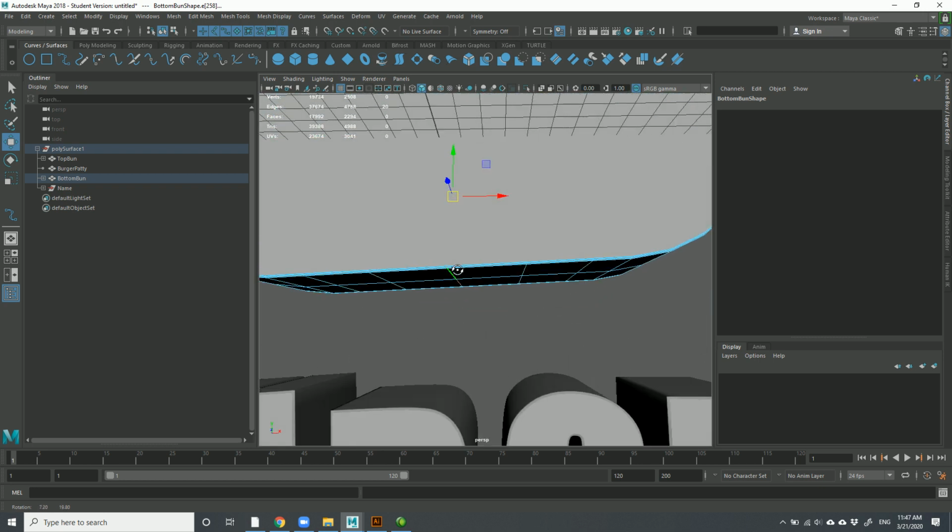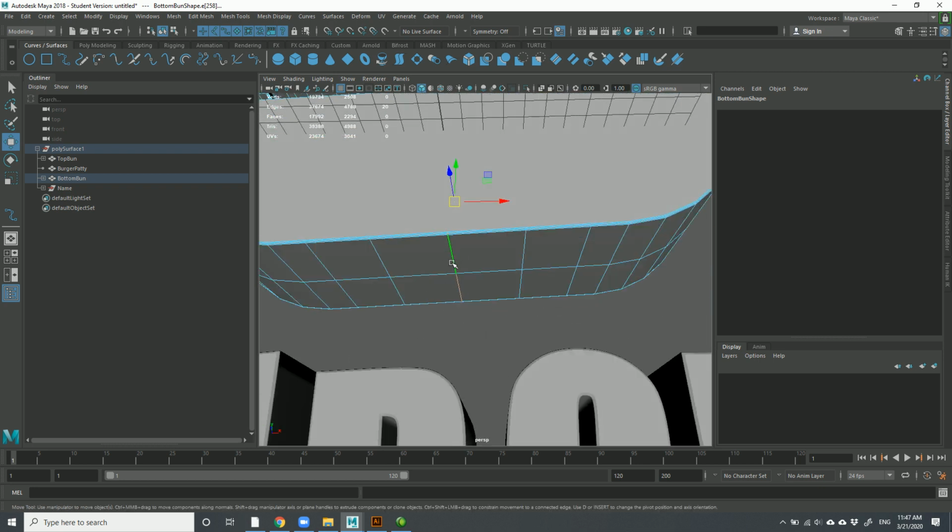Okay, yeah. And I'm going to convert this selection to vertices, so I'll press Control, right click, and this is such a handy little menu because you can convert. In this case, I've got some loops here, and of course the loop is broken here because it's not connecting up to the other side. But I've got this loop here that I'm going to convert to vertices.